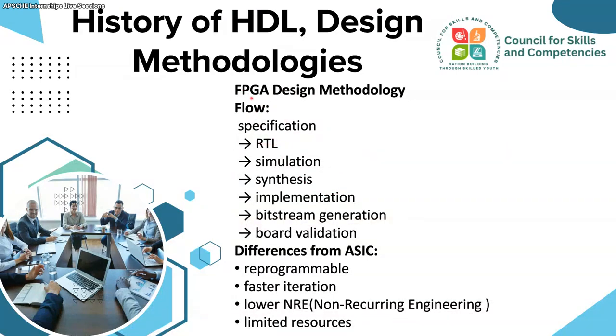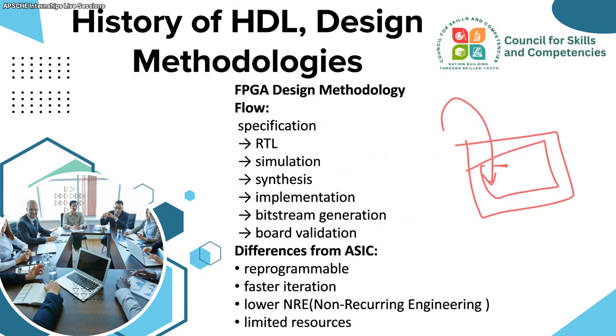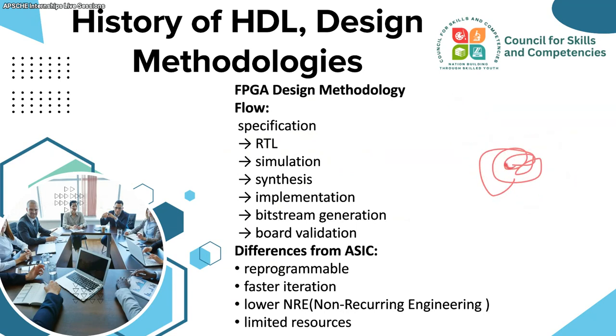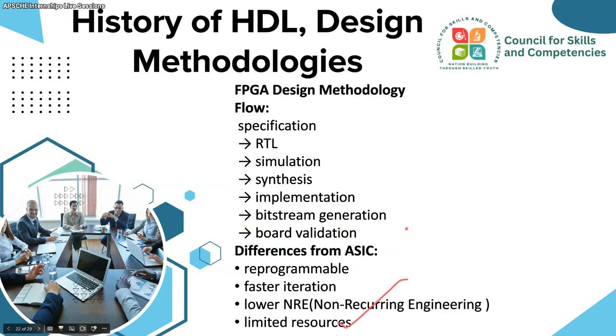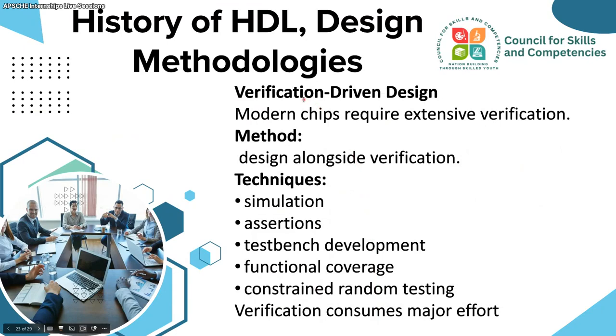Next, FPGA, where we write and design the hardware. In the hardware itself, we design it and we test it. That is where the FPGA design methodologies come in. There are RTL simulation, synthesis, implementation, and by the bitstream we put it on the board and check it. It is reprogrammable, with faster iteration, and it lowers non-recurring engineering costs, but has limited resources. So these are some of the methodologies.